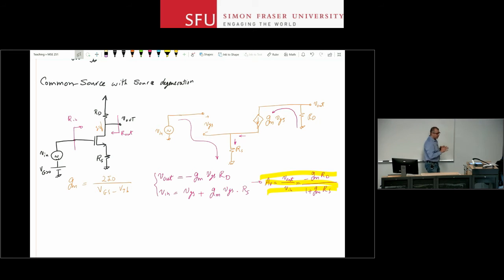So normally under similar conditions, you get a smaller gain out of a MOSFET than what you can do with a BJT. Of course, you can make your MOSFET wider, or play with all sorts of tricks that put the VGS very close to V threshold, so your ratio over there is larger. All those things you can do. But in general, for devices of the same size and the same amount of current consumption, you get more gain out of a BJT.